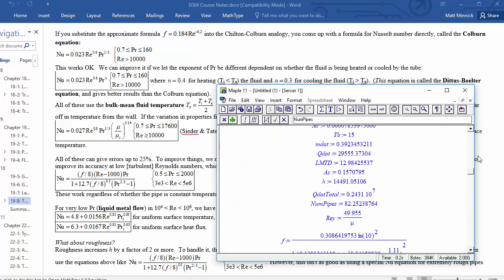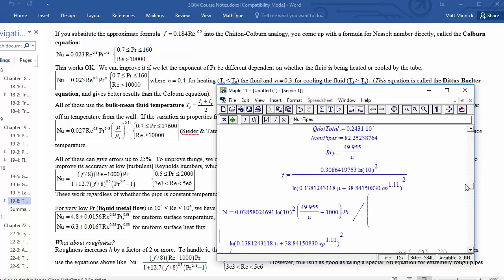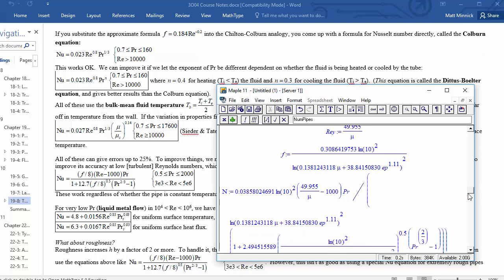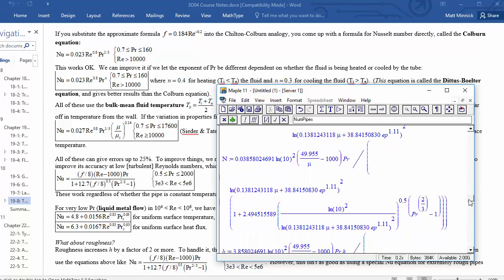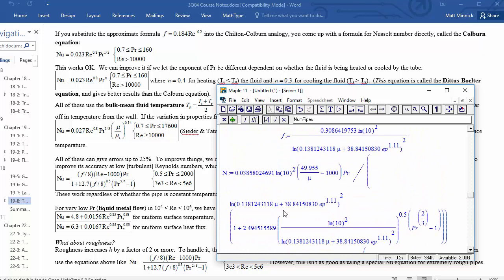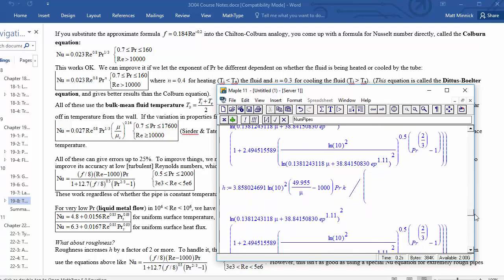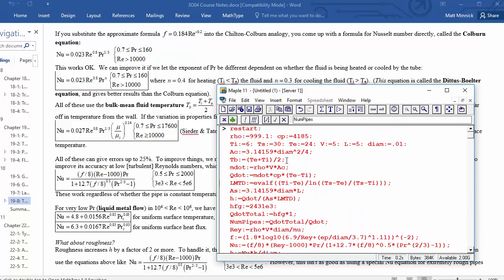It looks nuts because we need more parameters subbed in. Specifically, it looks like we need the dynamic viscosity, and we're going to need the surface roughness and the Prandtl number, and then at the end there, we're going to need... did we look up the conductivity? Oh, there it is. We're going to need the conductivity. Okay, so we need those 4 parameters. Let's go and get them.